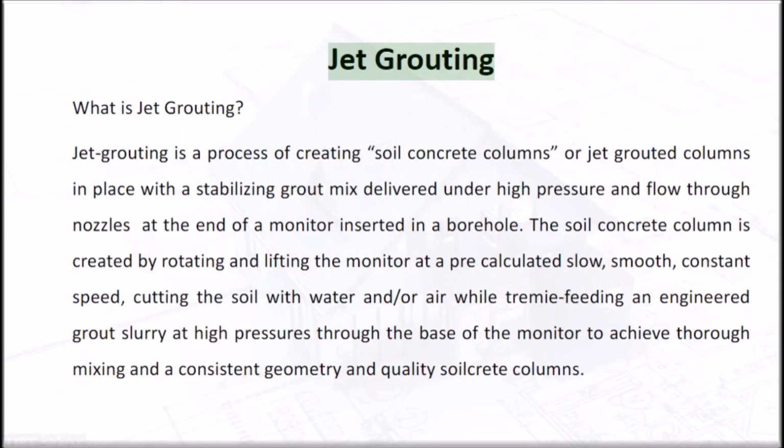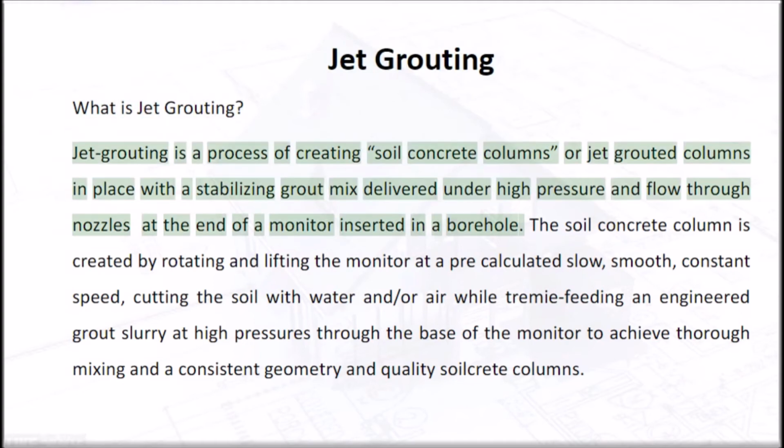Jet grouting. What is jet grouting? Jet grouting is a process of creating soil concrete columns or jet grouted columns in place with a stabilizing grout mix delivered under high pressure and flow through nozzles at the end of a monitor inserted in a borehole.